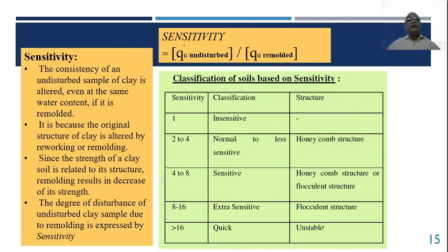Now, what this QU means, you will come to know afterwards. For shear tests in the laboratory, we conduct the unconfined compression strength test, wherein we take a soil sample. You can just assume this cross section is a cylindrical one, right? The diameter and height ratio is such that height is double the diameter, h is equal to 2d. Then this soil sample is compressed this way without holding anything on the sides. Just a vertical sample is put in the loading frame and compressed till it fails.